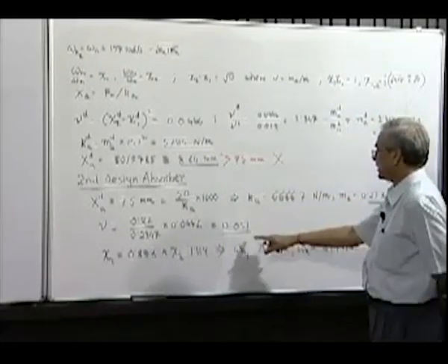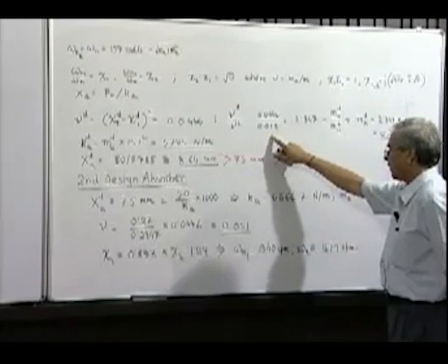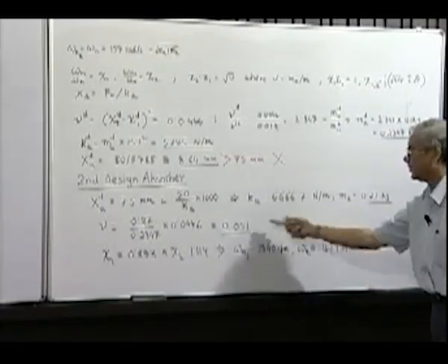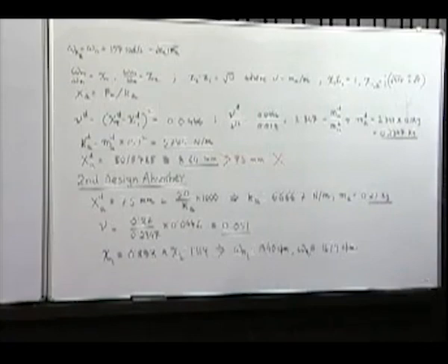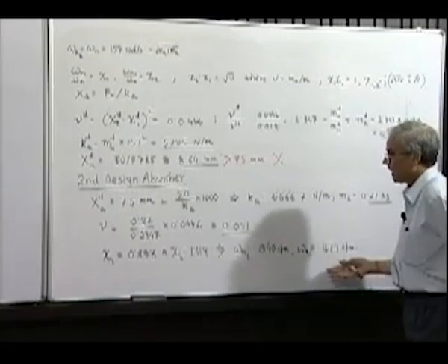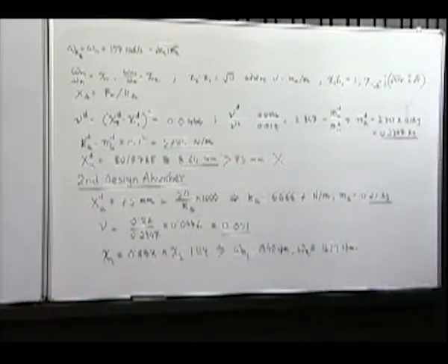So, if nu is this much, what will be the value of the trial mass? With this we can easily find. And once you know nu, directly this relation gives us the chi values, and the chi values are nothing but the natural frequencies divided by the natural frequency of the primary system or the exciting frequency or the absorber frequency, because they are all kept same in case of tuned oscillator.